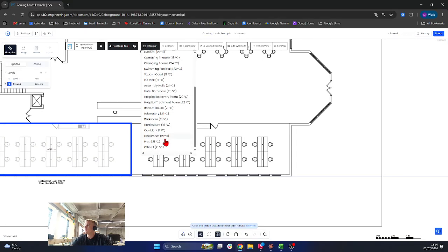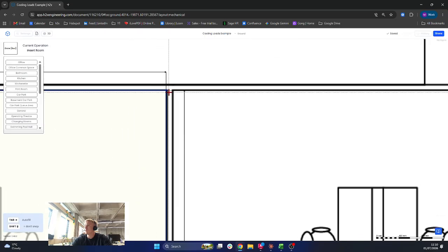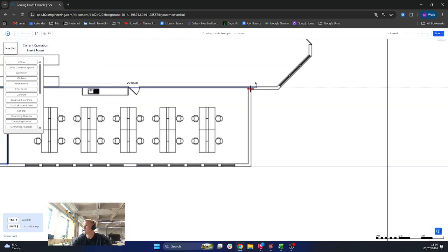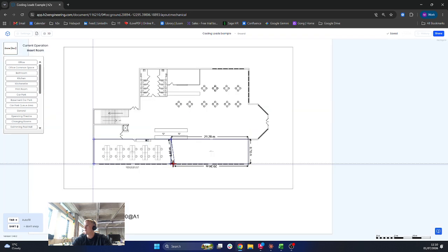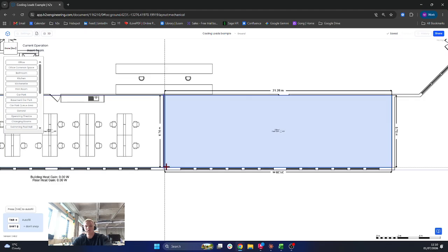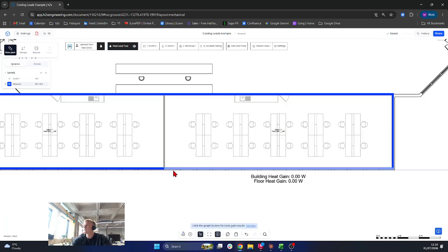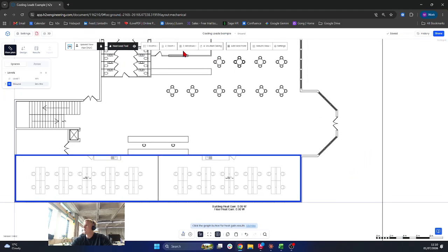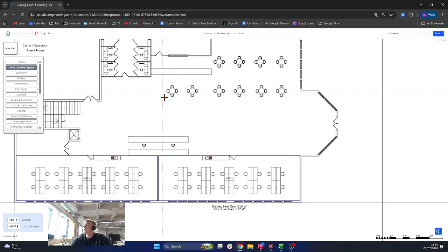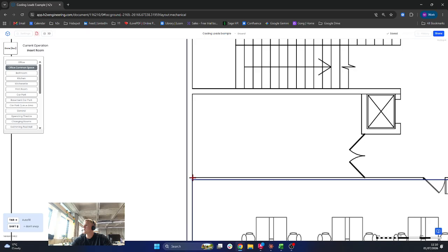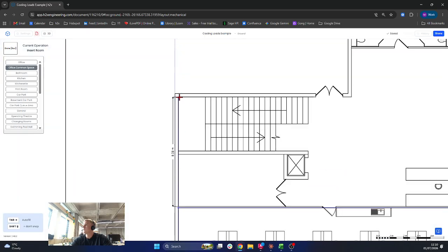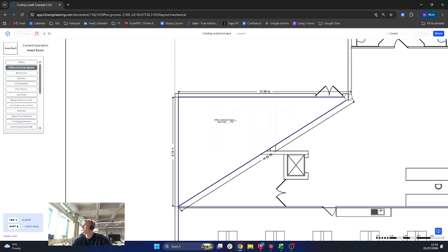When you draw an additional room next to one that's already been marked out on the software, H2X will automatically pick up the internal wall and differentiate it from the external walls. So you can see there, external walls are blue, internal walls are currently grey. Now, if I go up to the room tab up at the top here, I can draw in our office common space and do a left click here to start, left click here, bring that across.